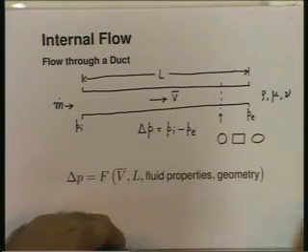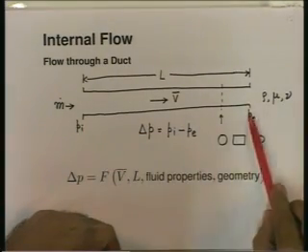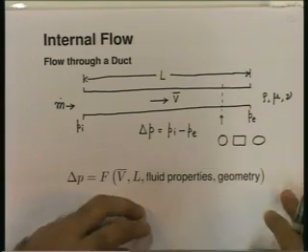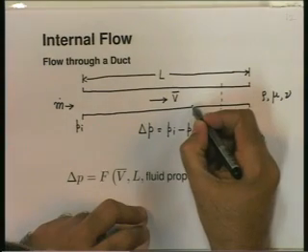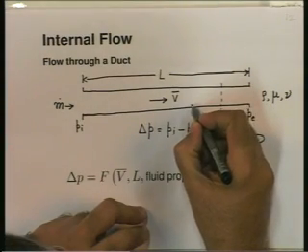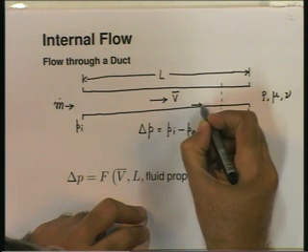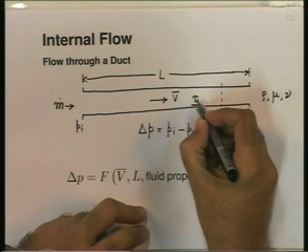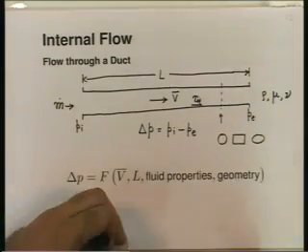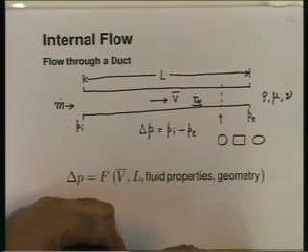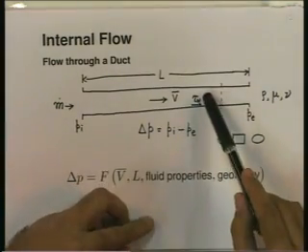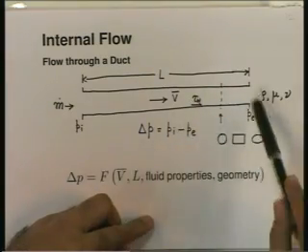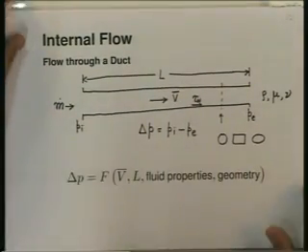At the gross level, we will be interested in the pressure drop. But because of the viscous action, there will be a shear stress acting on the wall. We may call it tau wall. In fact, we can relate the shear stress on the wall to the pressure drop through some simple geometric relation.